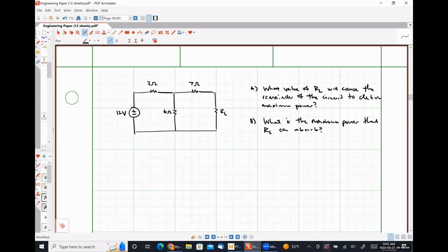Sorry, I drew that poorly. That should be a 3 ohm, but you're correct. We have a practical voltage source on the left-hand side. So Elizabeth, what would I replace that practical voltage source with? Four amps in parallel with 3 ohms. I agree wholeheartedly. So here is our 3 ohm resistor. Over here, we will put our 4 amp source. Did I get the direction for the current correct? Yes. Okay. So what can I do now?